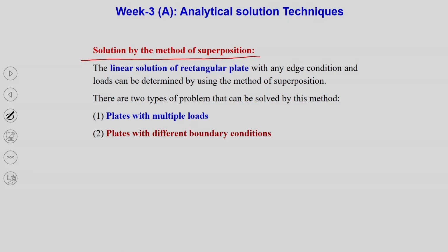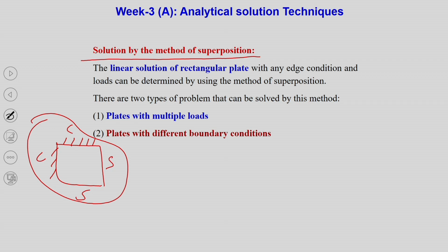Now I am talking about the method of superposition. This is a very powerful method. Let us say we are interested in finding out an all round, or some say like this, clamped and SS plate. Can we solve it with the help of Navier? No. Can we solve it with the help of Levy? No. Definitely we can solve it with the help of the principle of superposition. So you have to know where we apply the principle of superposition.